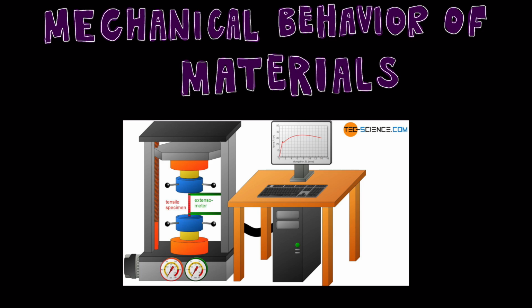We'll have an extensometer, potentially some load cells, and strain gauges, and then we will hook all of that instrumentation up to a data acquisition system and a computer. And on that computer, we will read out the force elongation curve. That force elongation curve is going to tell us how our specimen is behaving under increasing load or elongation. So let's take a look at what a typical force elongation curve might look like for a ductile material.